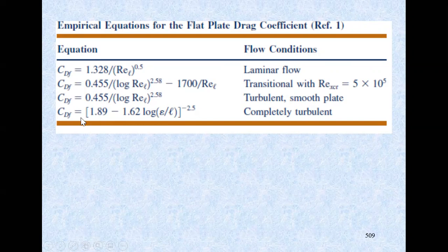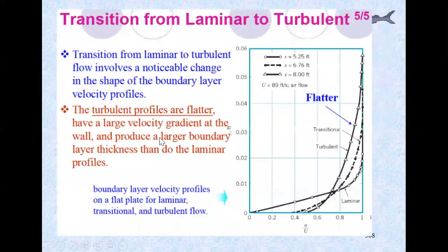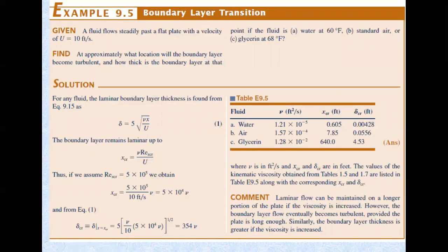How come this happened? Well, you can consider this one as completely turbulent because it's a really small part of laminar, then you suddenly have turbulence. So for water, for example, in our case, we can assume that it's all turbulent. While over here you have a considerable length of laminar before it goes turbulent.